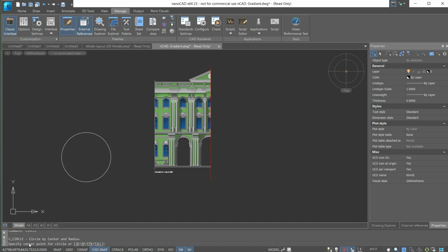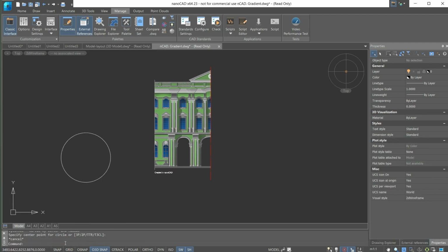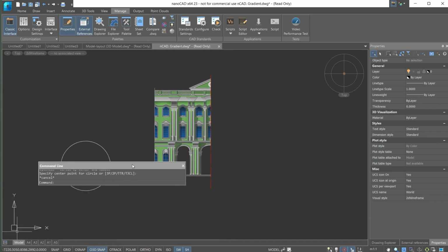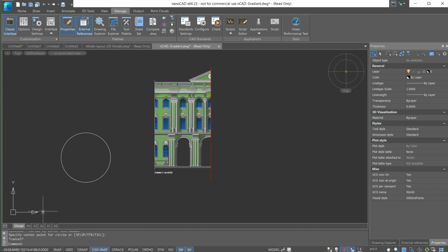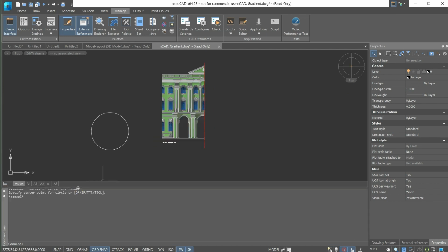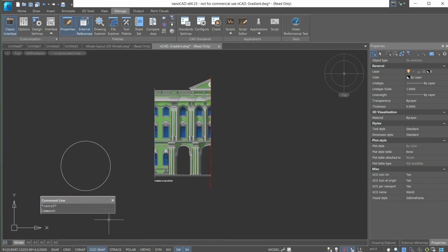If you notice, when the center of the circle is specified, a list of options is provided. We will explore what this means and how to work with it later on. The command line also has its own context menu, which allows you to make it floating, pinned, automatically hidden, or completely hidden. Just like the regular functional panel, you can resize it if needed. The command line can be moved across the graphic drawing area.